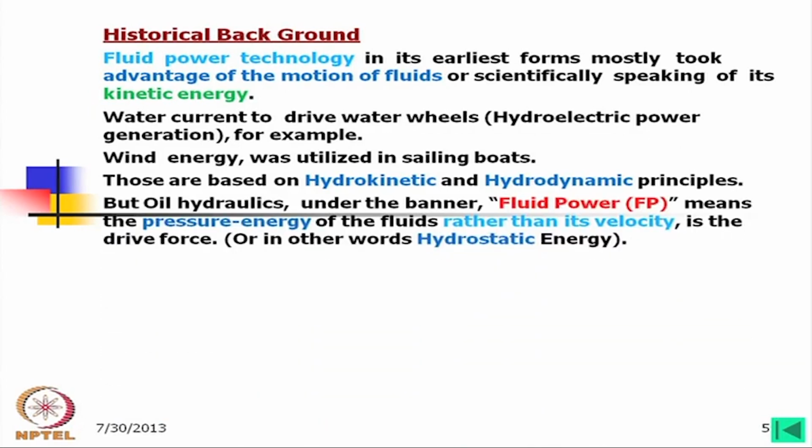But oil hydraulics under the banner fluid power means the pressure energy of the fluid rather than its velocity is the drive force, or in other words we would say that we are using hydrostatic energy in case of fluid power.